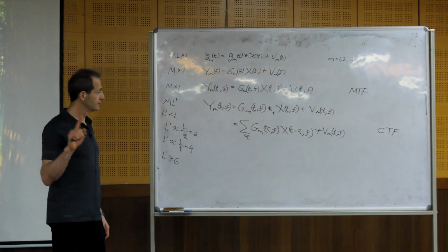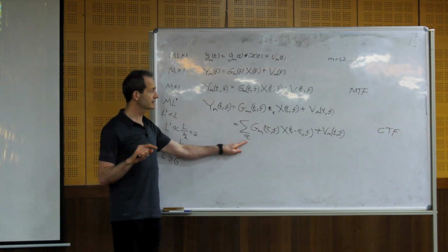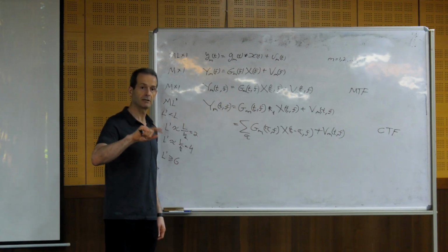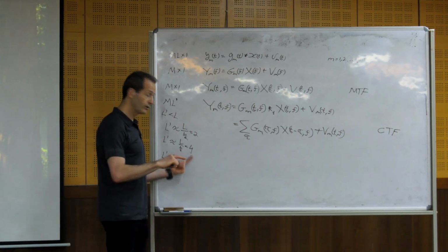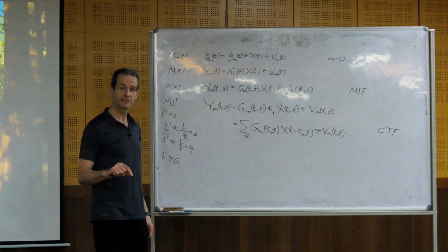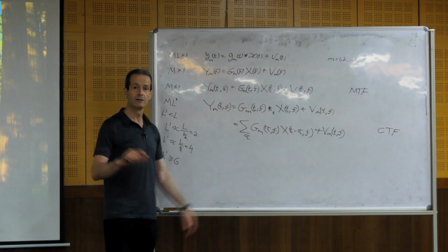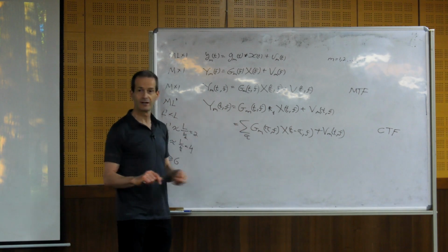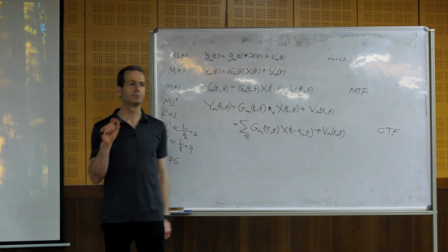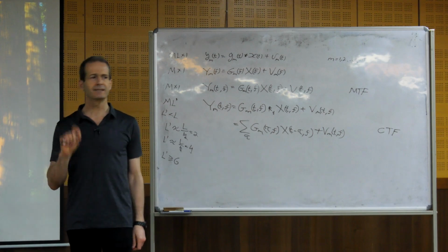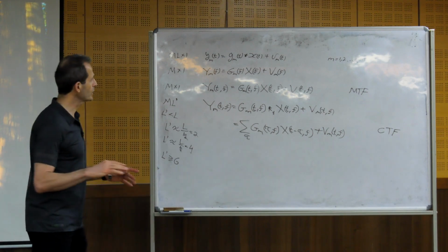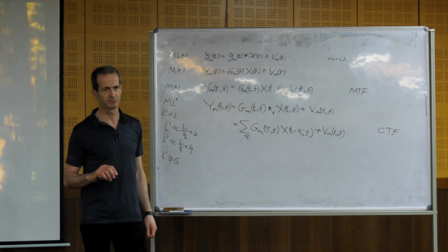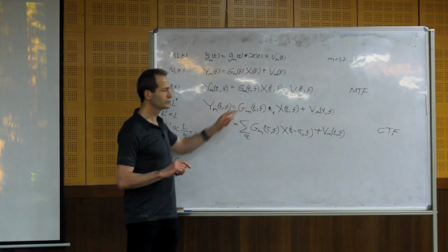And also, you see here, tau doesn't start from 0. It can start from -1, -2, depending on the overlap. So with 75% overlap, sometimes we start with tau minus 2. So it can be from minus 2 to 4. So pay attention to these important details when you work with a problem and you want to implement it in the STFT domain. This is very, very important, how you define the problem.